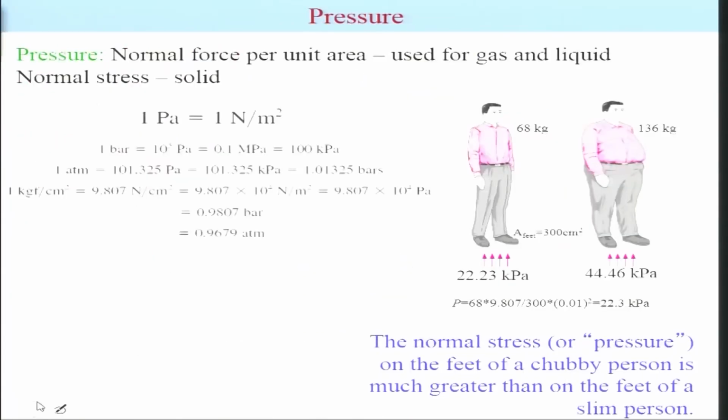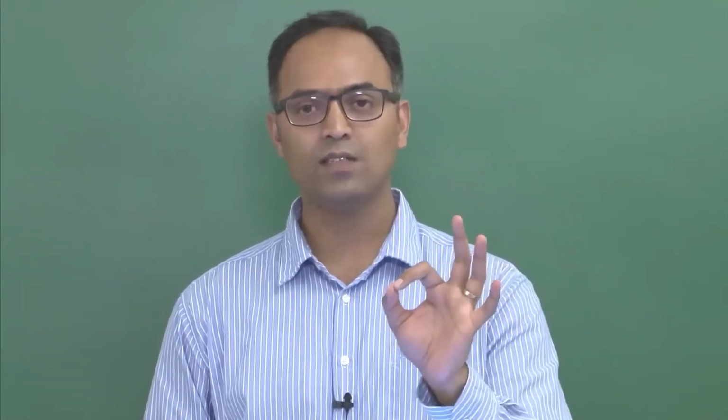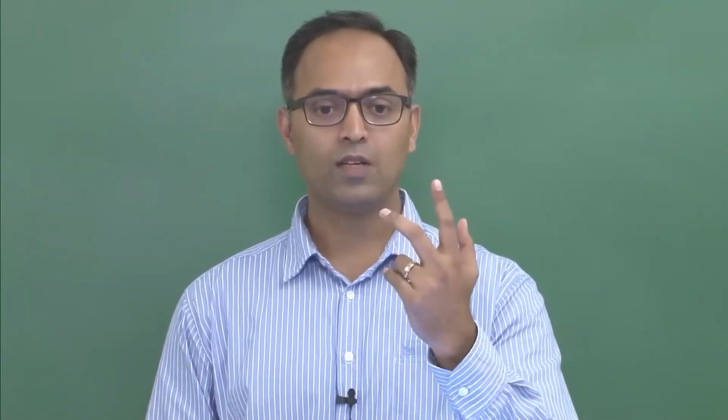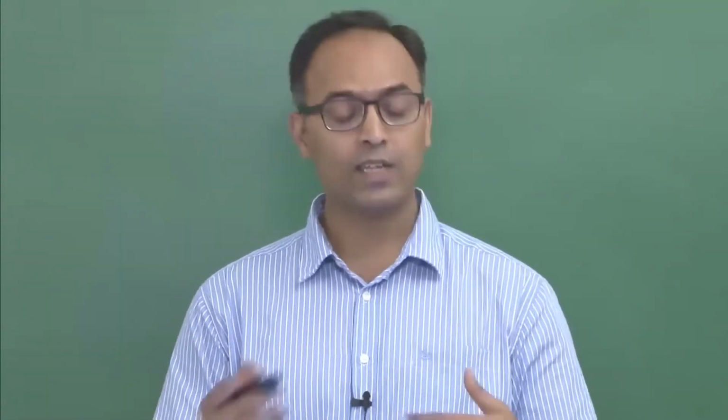Okay. All right, so the other unit which we are going to use: we are talking about intensive variables, which are extremely useful. We talked about how you can define the state of an incompressible fluid by providing two intensive variables. For a single phase, temperature and pressure is fine, or you can use temperature and specific volume. Specific volume is variable even if there is a phase change, such as water going from liquid to vapor, but the pressure is dependent on the temperature when there is a phase change. So we talked about that. Pressure is an extremely useful quantity for our thermodynamic analysis.